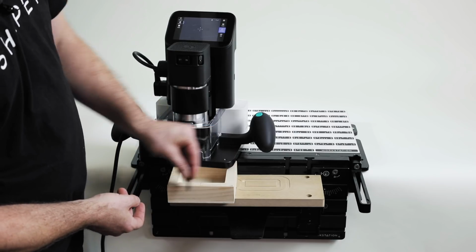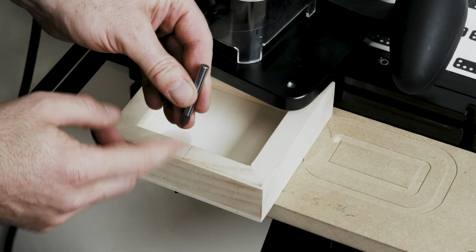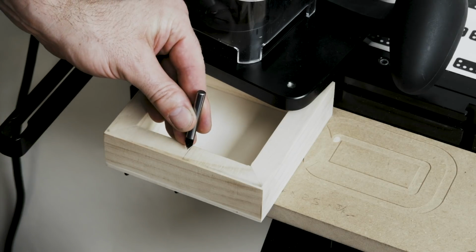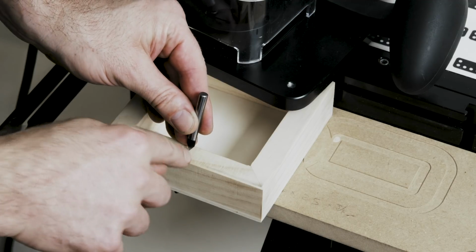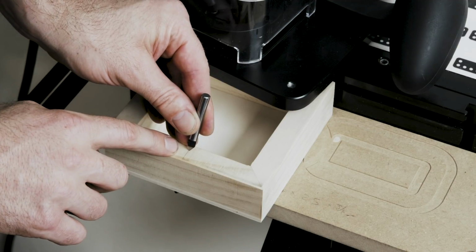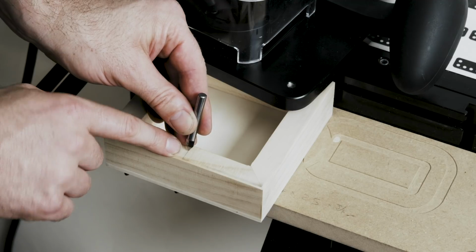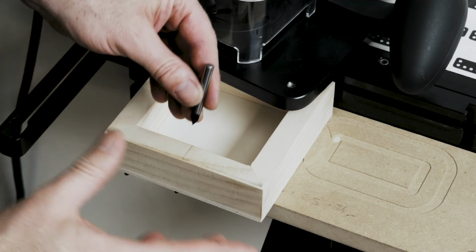There's then a hybrid approach, so it's probe 2 points. You would use the cutter with a point, so the engraving cutter, and then raise the cutter up and then visually probe the point of the cutter itself hovering above an actual line. So you would confirm you're exactly aligned with the pencil mark and then probe using that approach.